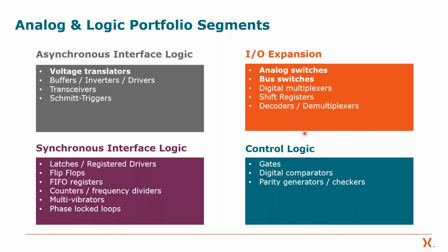In the upper right is actually the biggest growing area based on that history trend that we just saw, this idea of I/O expansion. A pin on a microprocessor is pretty expensive because there's already a lot of pins on them. I mean, modern processors have thousands of pins on them. To add a pin there is relatively expensive. It is better from an efficiency standpoint, as well as sometimes just from a simple board routing standpoint, to put your I/O on an expansion port outside.